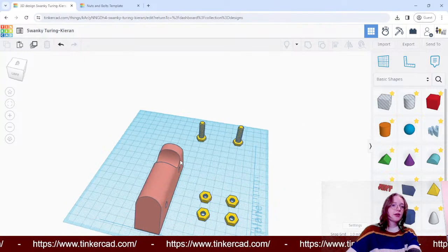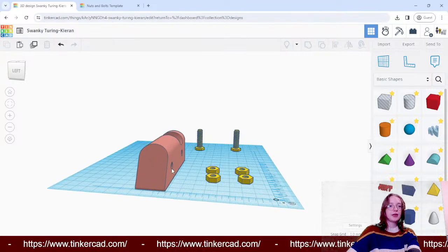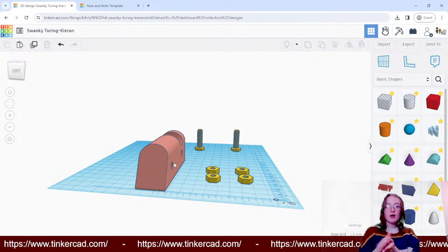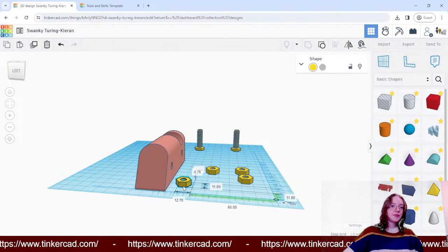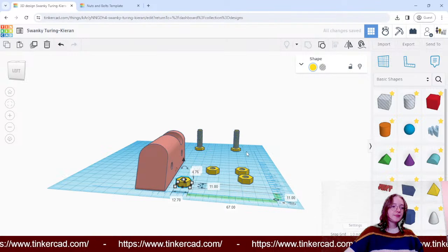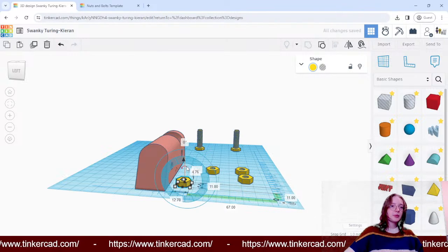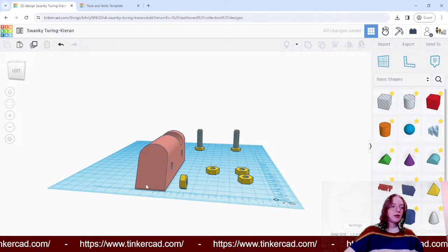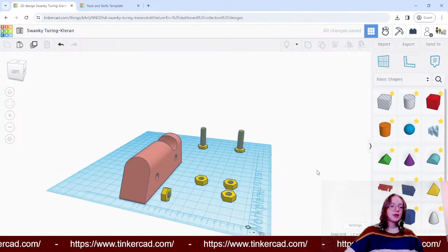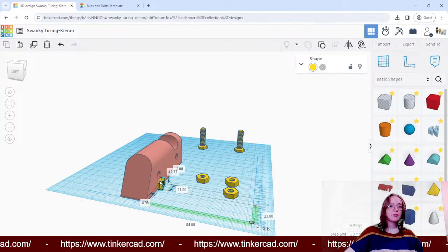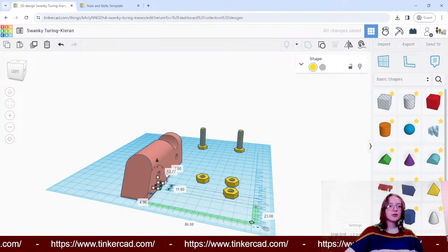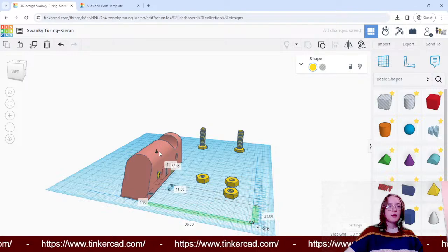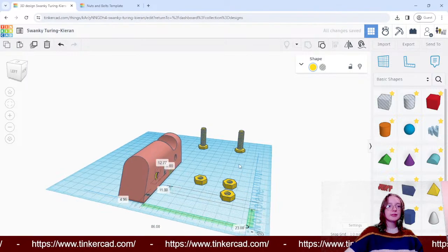And we are going to want to place them kind of against these holes that we've created, but flush with the surface of the car. So what we're going to do is we're going to select this. We're going to give it a flip of 90 degrees. And so we're going to make sure that we move them so that they're flush with the wall, but that the holes are aligned.